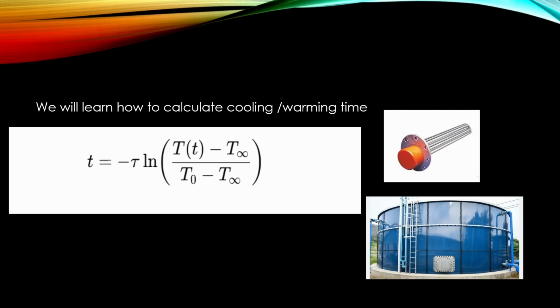Then we in industry typically have this kind of questions. We need to calculate the time to cool down a vessel of, for example, water or warm it. If we have a fixed heat transfer unit there and it's having some maximum power, we need to calculate the time, how long time we will need to get the temperature of a liquid to increase from one temperature to another.